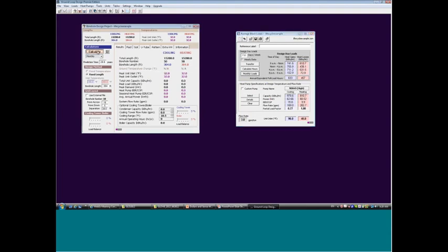So I'm going to hit calculate, do a 20-year simulation. Okay, so it's telling me my predicted inlet temperature for cooling is 83, which is very moderate. Gives me a high performance. My predicted EER is 18.4, kind of on my worst day of the year. And my average seasonal performance is predicted to be 20.6, and this is the number we're going to want to use for our life cycle cost because it's our average. On the heating side, my temperatures are relatively moderate, and I have pretty good COP values.